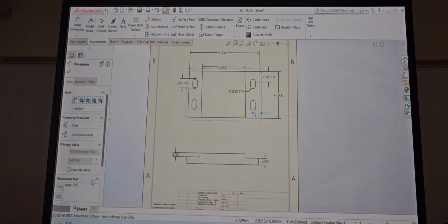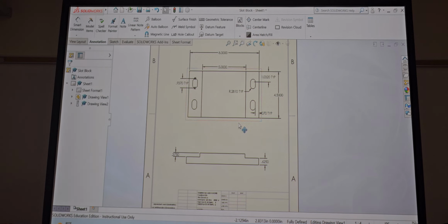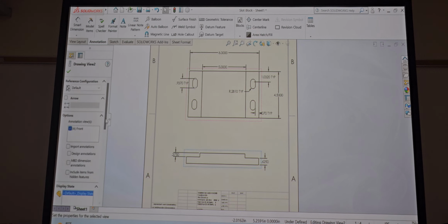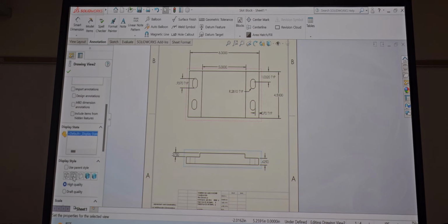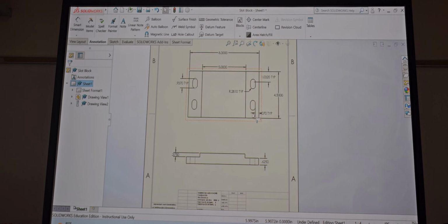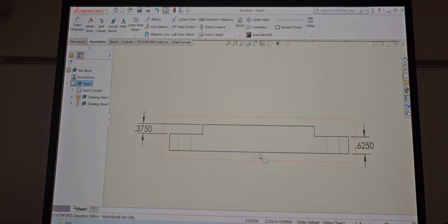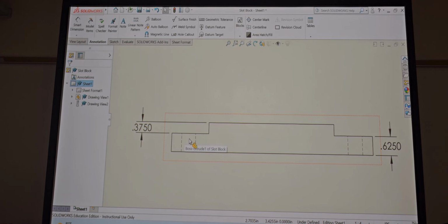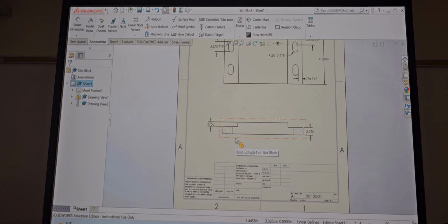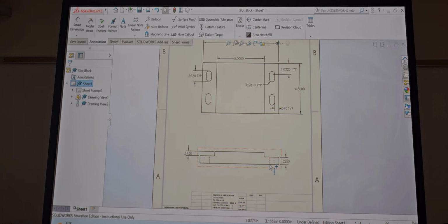And you also do the hidden lines for the front view. Yeah, so down here, I would click on this one so that it shows the slots going through, correct? And normally by ANSI, if you have something going through like that, or it's a hole, you will need a center line also. But with that, we know that it's going through, correct?